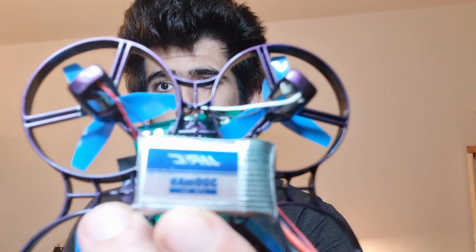So these hobby ones will not work. The batteries have a discharge C value, and this discharge is not high enough for the drone. The motors can take a lot of amps. I think it's taking over 1 amp each, so 4 amps in total, where you can see a drone battery will have 15C at the bottom. Can't see, but that's your discharge rate.